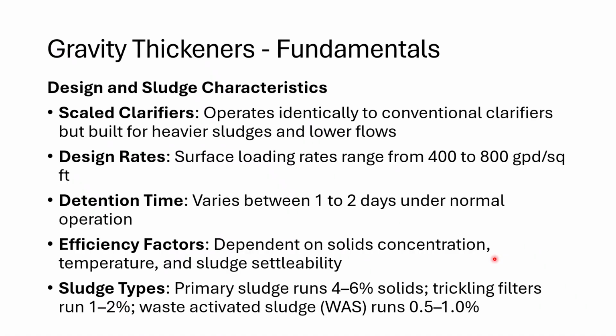Okay. The efficiency, that's going to depend on a few things: your solids concentration, the temperature, both the ambient air temperature as well as that of your waste stream, and the settleability of the sludge. That's what's going to dictate how efficient these thickeners are.